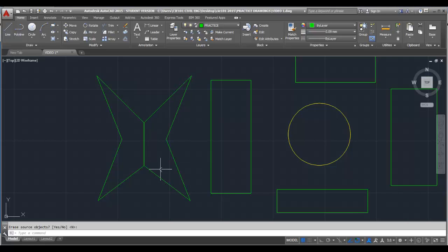And then if I want to, because this is a polyline, I can ungroup that, hit escape, and it's still one piece. So what would happen if I hit trim, enter? Can I trim that? And can I trim that? So you can trim element segments out of the top.